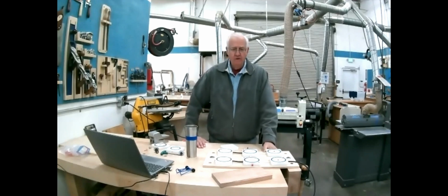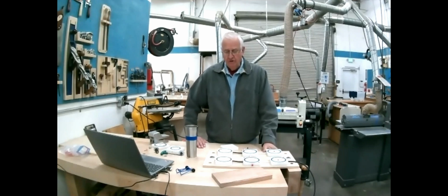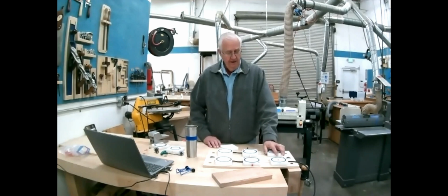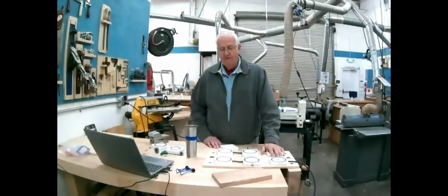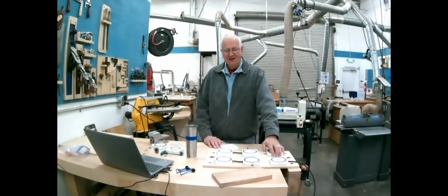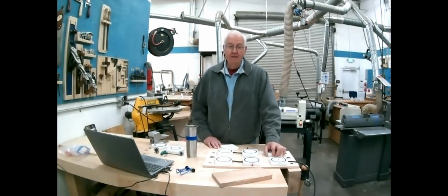If you look at the big commercial ones, they use the ultralight MDF, but they take big pumps. The one up at Palomar, they've got a 4x8 sheet that they put down. They use MDF in it, and they suck through the MDF, but they're using 2 5-horse vacuum pumps. They're both 3-phase. That thing's sucking a lot of air. So you can put a 4x8 sheet down and completely suck it onto the table.